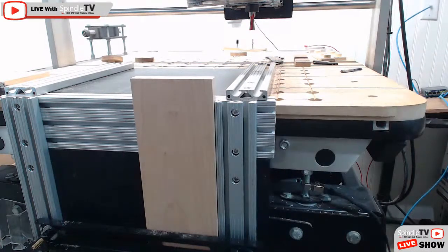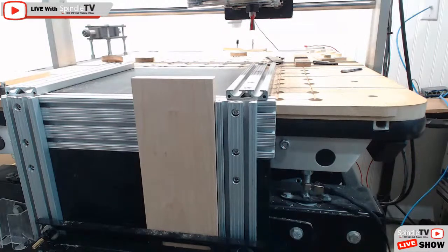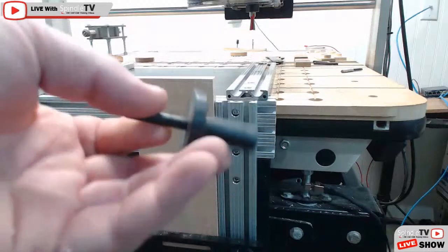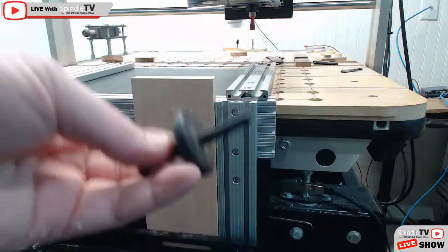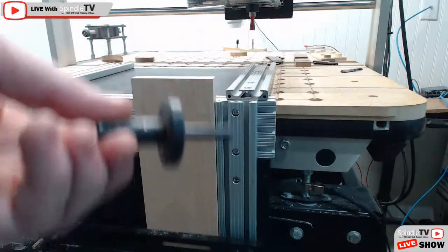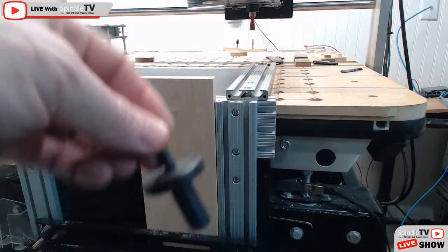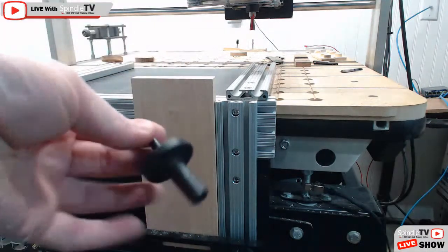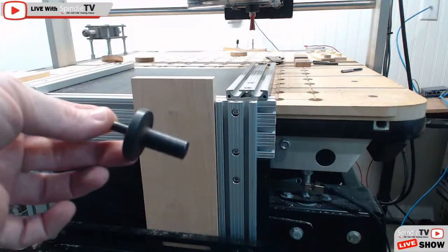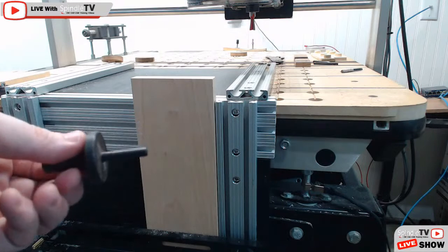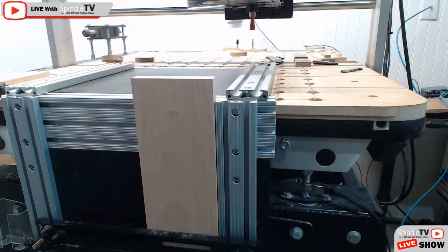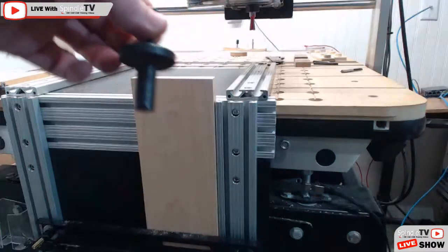It's evading me. Now, for those of you that get the digital wood carvers with your Hitachi router, the basic default router, you'll see one of these things in the box and wonder, what in the heck is that for? Now, this is not designed as an alignment pin for the CNC. It's actually designed when you're putting different bases on a handheld router. It's got a 1/2 inch diameter shank on one side and a 1/4 inch diameter shank on the other. So I simply use this as an alignment pin.